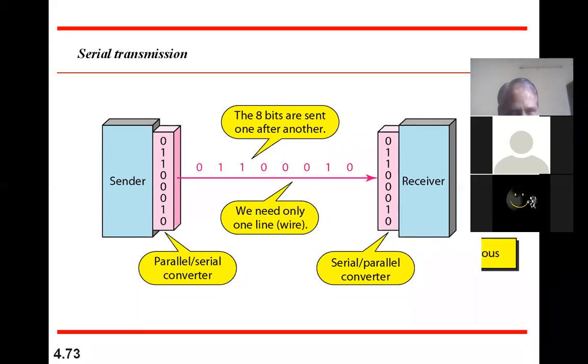But because it is 1 bit per clock pulse, it becomes slow compared to parallel communication. At the same time, it becomes less expensive, less complex, and more reliable, because maintaining one line in good condition is easier. You may say that if that line fails, everything fails, but whether it's one line or multiple lines, a failure is a failure, so there's no such difference.